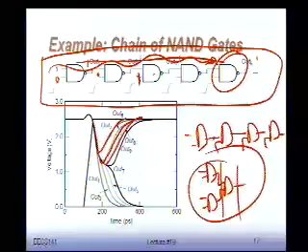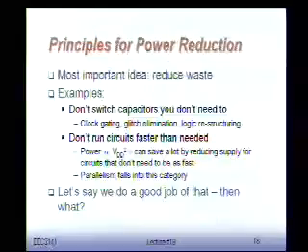If you're not careful, with big logical structures like multipliers, glitching could actually become a sizable chunk of your power dissipation. It could be 30%, 40%. So it's worth looking at, because some small topological optimizations can improve your network substantially. Okay?